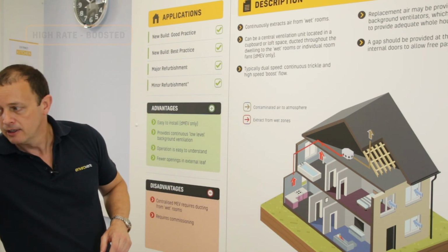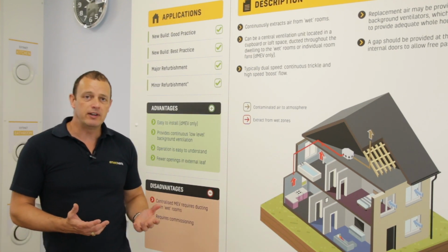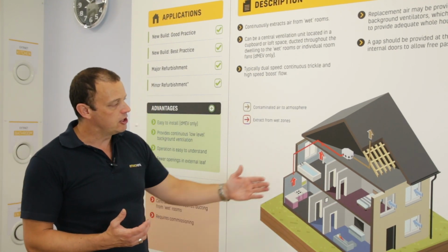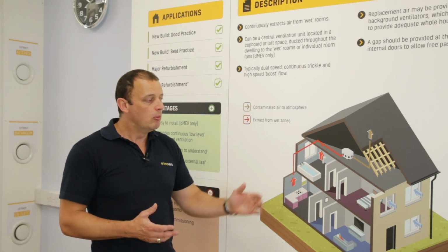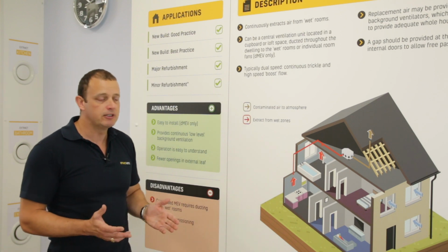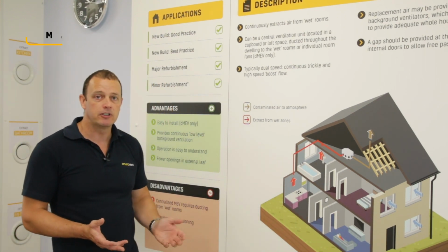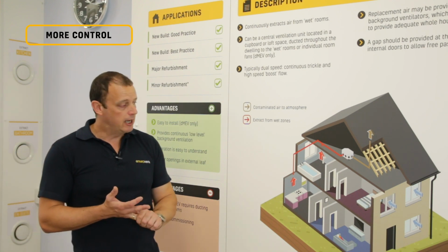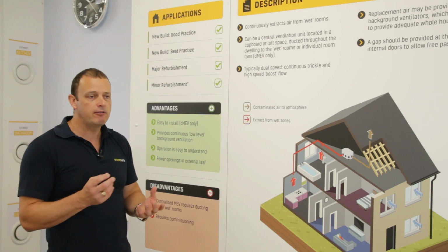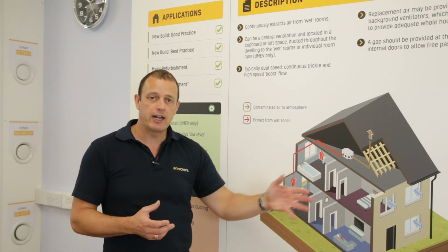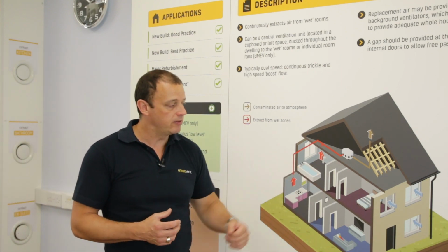It's a much more beneficial and energy efficient way of ventilating. A lot of people have concerns because it's running all the time, you've got high energy consumption, you're losing a lot of heat out of the dwelling, but it's more controlled than your standard intermittent fans. Because you've got something running at a low rate, it's using less power. So they actually use less electricity, and they don't extract as much heat, because when they're on a low rate, it's a very low rate. It's a lot less than what the natural leakage would be in an old house. So it's more controlled and it's better for ventilation.